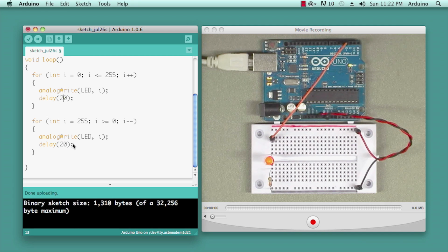So this technique, this analog write, is useful for blinking or fading LEDs up and down. It's also very useful later on when you are controlling electric motors, especially using something called an H-bridge, which I'll give you some references for in the supplemental materials. So this would be the exact same way we would change, for instance, the motor speed of a robot's left and right wheels to go from 0 velocity to full velocity.